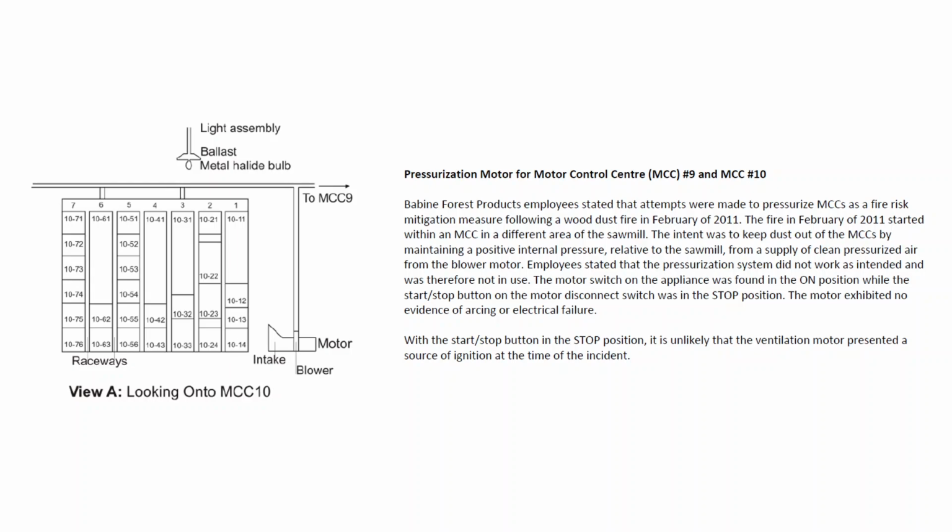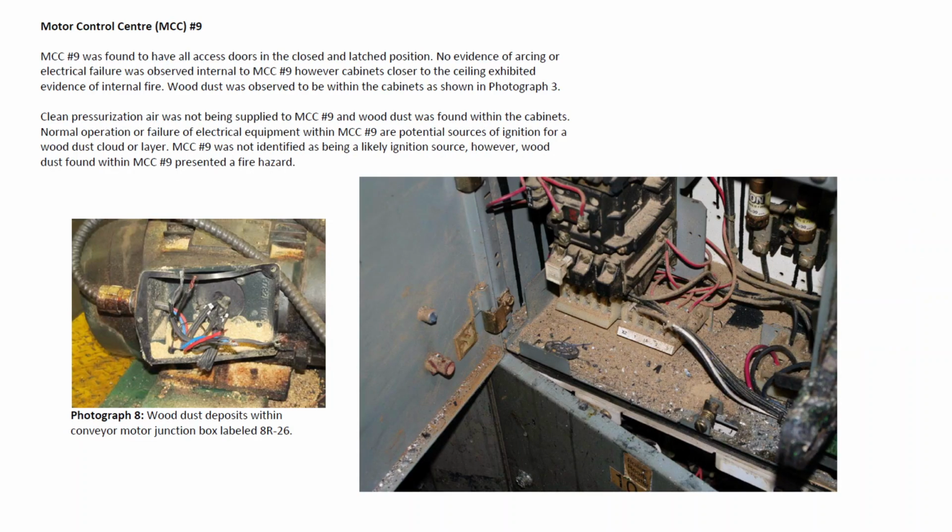Now, was that the fault of the electrical contractor? Well, that's certainly something to be discussed at a later date with more information when they finally get to that point. But at this point, it appeared that it was the actual users of the facility which may have shut it down. What this caused was significant accumulation of dust inside the motor control center, which was not rated for that application. So if you have lots of dust accumulating in a non-HAZLOC enclosure, at a certain point, if you get a fault, you're going to have a much larger problem because it's going to ignite the dust.